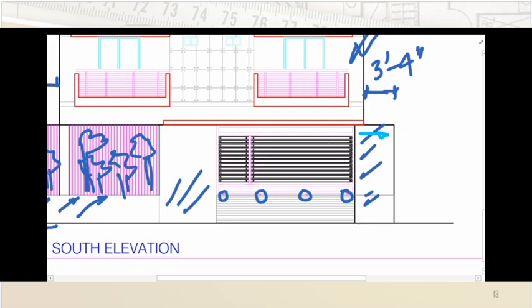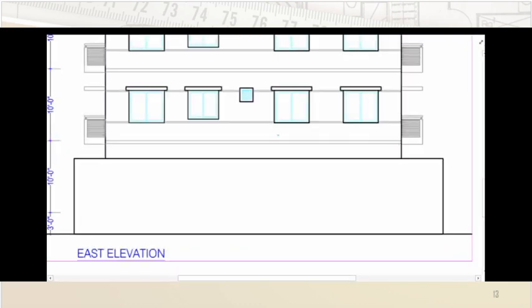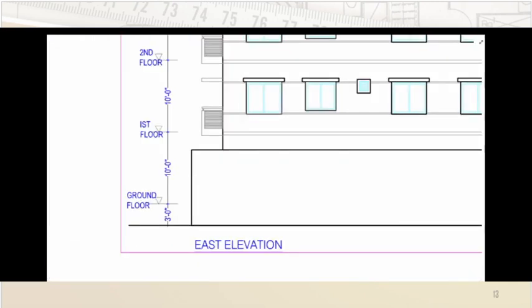It cannot accommodate enough space to open up. That's why. However, same as we have discussed, this will be 3 feet and 10 feet. So the boundary wall, we can say, is 10 feet from the ground level or 7 feet from the plinth level. This is actually the plinth level. Okay, the east direction. So when we come to the east, let's see the typical plan.